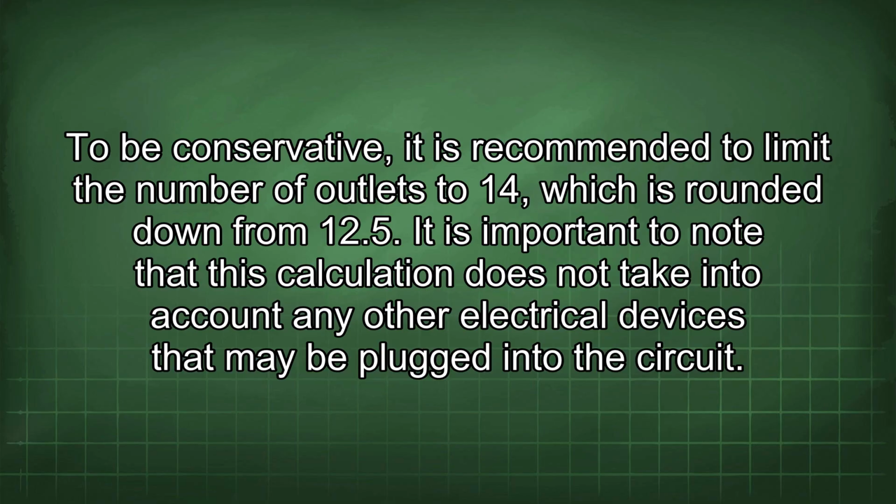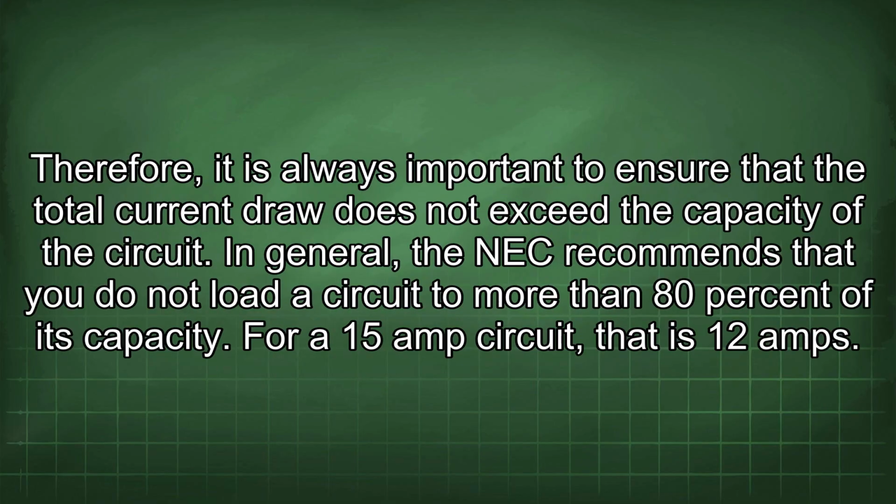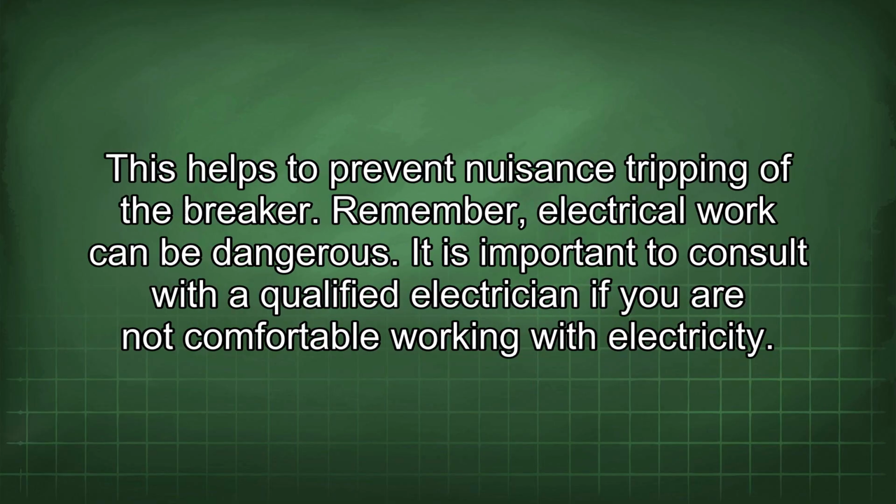It is important to note that this calculation does not take into account any other electrical devices that may be plugged into the circuit. Therefore, it is always important to ensure that the total current draw does not exceed the capacity of the circuit. In general, the NEC recommends that you do not load a circuit to more than 80% of its capacity. For a 15-amp circuit, that is 12 amps. This helps to prevent nuisance tripping of the breaker.